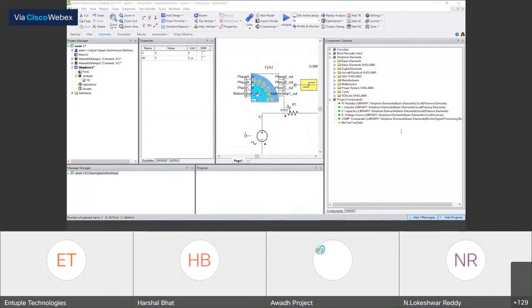There is one question. Can the simulated data support the plotting of hysteresis curve? Yes, it can. The hysteresis curve is generally an input quantity, but if you are doing magnetization and demagnetization, like vector hysteresis, then the hysteresis curve does change during simulation, and you can plot the new hysteresis curve. No problem. At any point, you can plot it.